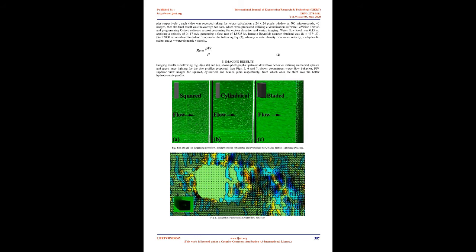PIV is utilized in several research fields. Commonly this technique measures the instantaneous velocity distribution in 2 dimensions, by means of photographic movement determination of immersed tiny spheres in the water flow in a plane during a pretty short time lapse. PIV measures the distance, s, traveled by immersed particles, tiny spheres, in a moving flow during a time lapse, T, where U means the velocity obtained under the following Eq. 1. Fig. 3. PIV equipment and water channel.